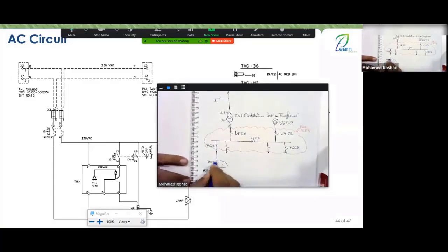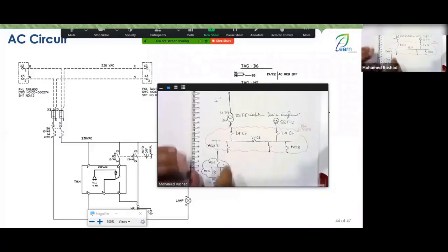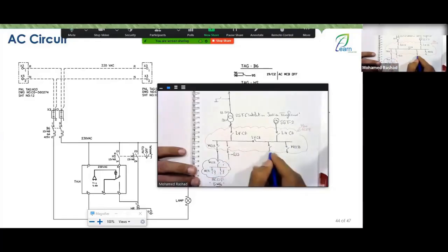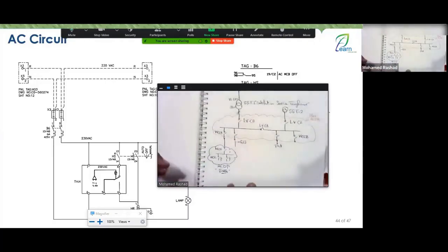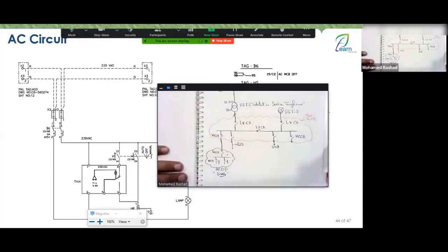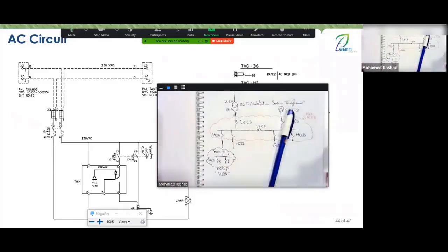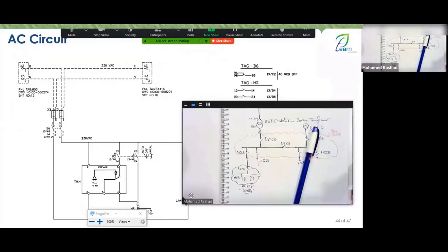Okay, engineers. Okay, we call it an AC distribution board, but this is specific to the switchgear, for example, in a building. This is specifically for supplying the AC circuits located in the switchgear. There is another one that might supply, for example, what you have in the GIS. Another one might supply your protection panels, supplying them as they operate through any location you have in the station. All right, that's great. Now, regarding what you have in the station, keep in mind that I will return to this diagram when I enter, but for now, I will continue with our circuit.